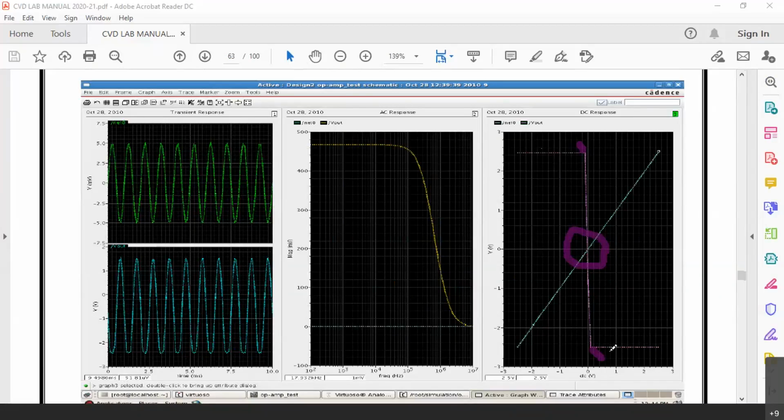So that is the advantage of using MOSFETs when compared to BJTs, that the biasing arrangement is simpler in case of MOSFETs when compared to BJTs. BJTs require a complicated voltage divider bias network at the input to set the Q point. Whereas in the case of MOSFET, such complications are not there. Moreover, when we use dual power supply, the effort for fixing the Q point is minimum there.